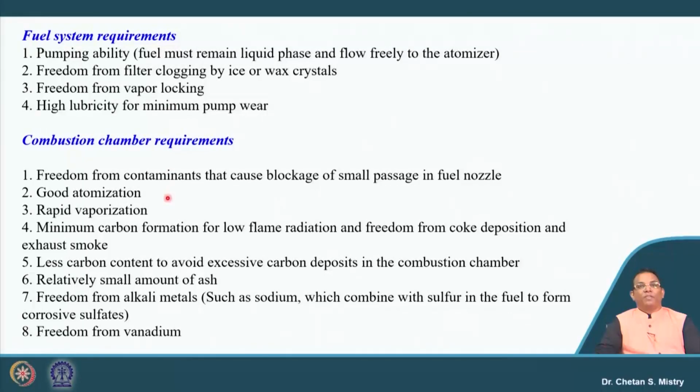At the same time, for the combustion chamber, the fuel should be free from contaminants that cause blockage of small passages, because we are using fuel injectors and fuel nozzles which have smaller dimensions, since we need to do atomization. Let me put the point here: your atomizer, your fuel injector, should make the droplets as tiny as possible, then only will it give good atomization.